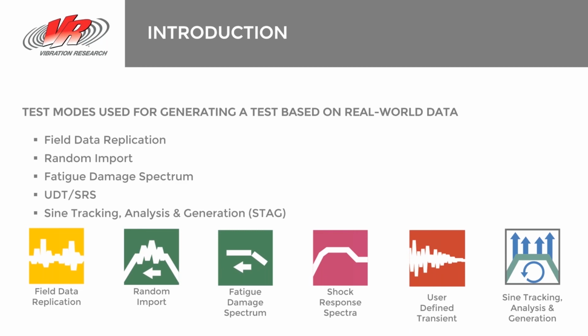So as part of this, we have gone through and created a procedure and the appropriate analysis tools for analyzing the rotational component, extracting that from a time history file, building a sine tone profile or series of profiles that are appropriate and can be accelerated for the rotational sinusoidal environment.